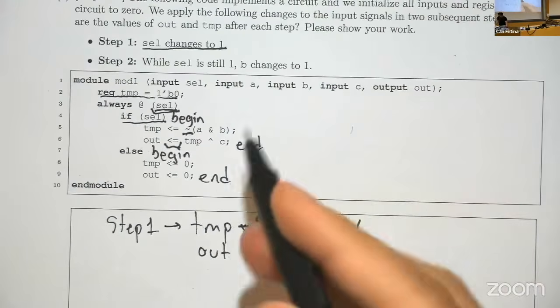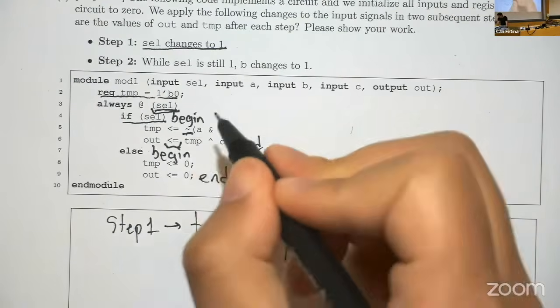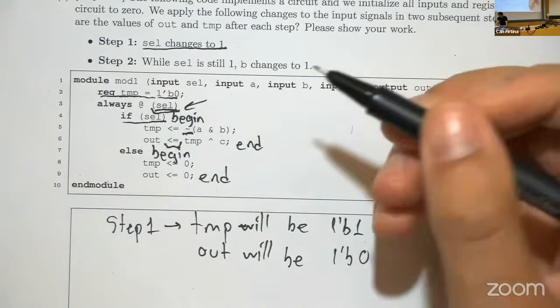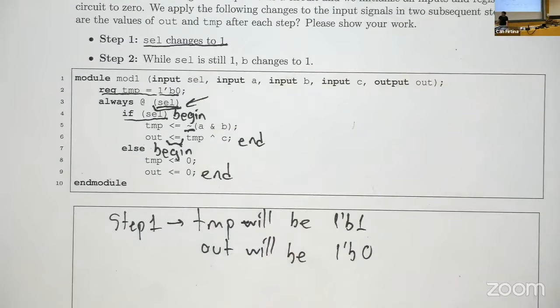So in step 2, while select signal is still 1, we change B from 0 to 1. This won't do anything, because if you check the sensitivity list of this always block, it's only select. So this block will be executed only when the select signal changes value. When the value of B changes, nothing will change. The block won't execute, basically.